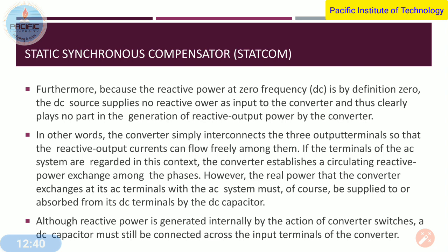A DC capacitor must still be connected across the input terminal of the converter, but there is no role of the DC capacitor in the generation of reactive power. The reactive power is generated internally by the action of the converter switches. That's why we are saying that reactive power at zero frequency is by definition zero, so the DC source supplies no reactive power as input to the converter.